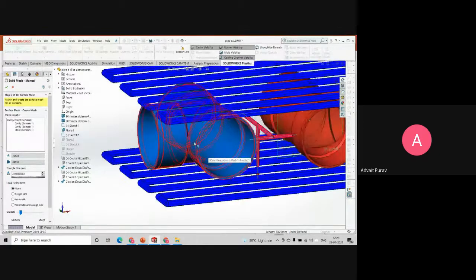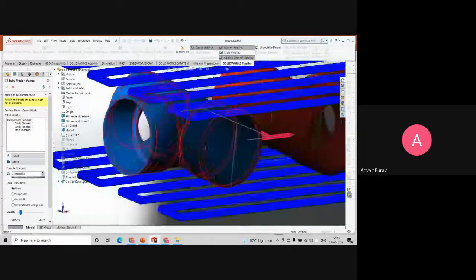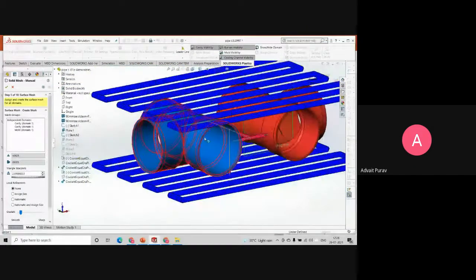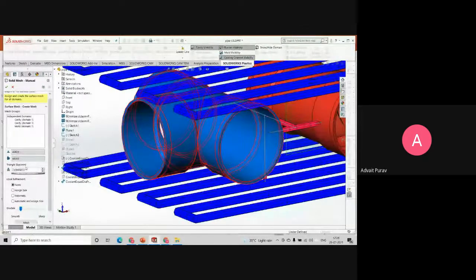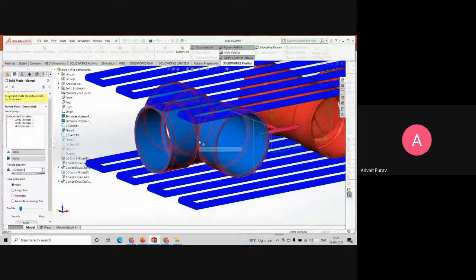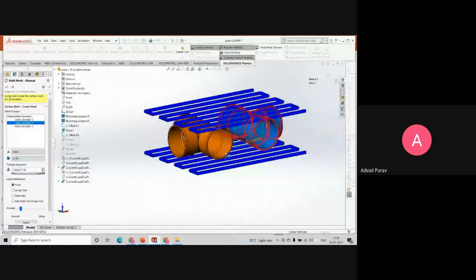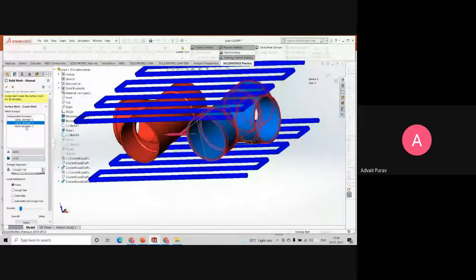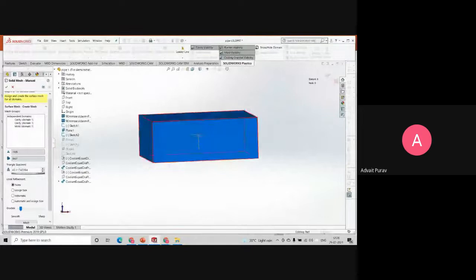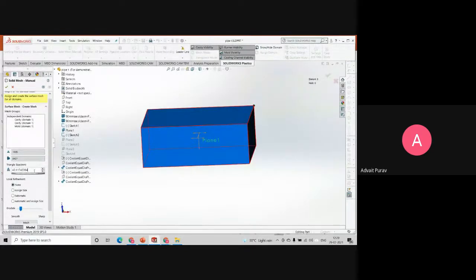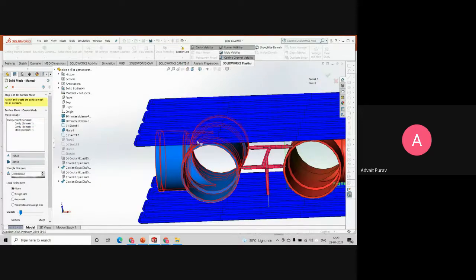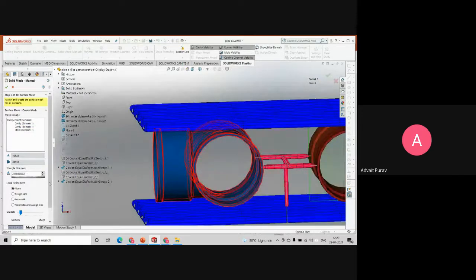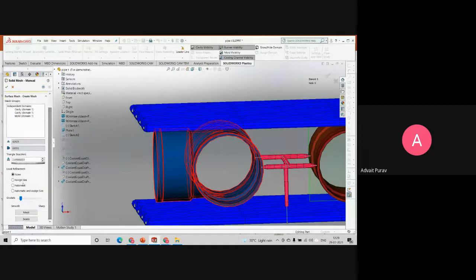Okay. Now in this you have to assign a particular size to your domain. For this cavity, I have assigned size 2.69. The software had suggested this previously, and this other part is also around the same, 2.65. But the outside mold I have kept at size 43. The reason being it's a large figure, so the meshing size has to be larger. But for this one I have kept 2.69.